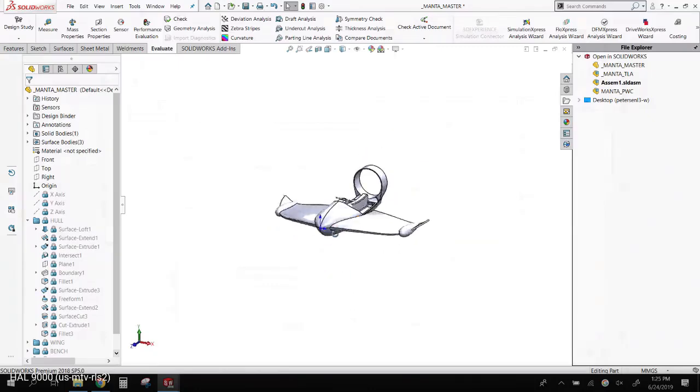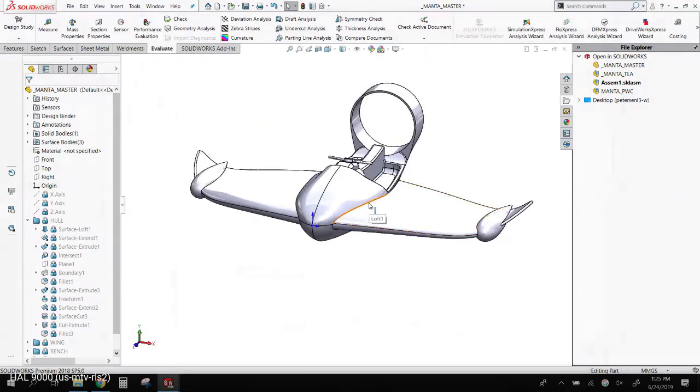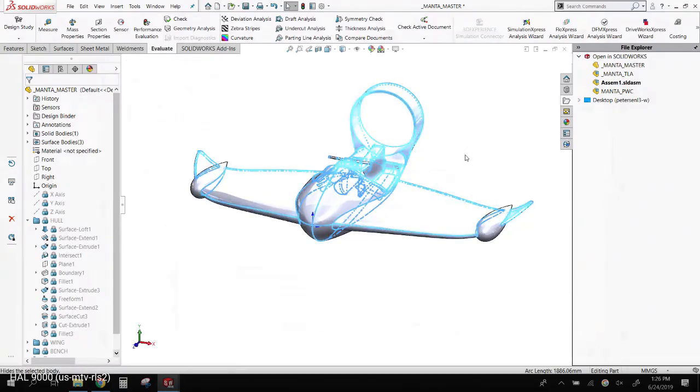All right, let's start with some more wizardry here. I learned this one from Brad Williamson's, and I've been using it ever since. If you select anything and you hit Control A, what's Control A do? Select all, typically. So if I pick an edge and hit Control A, it selected every edge in that part.